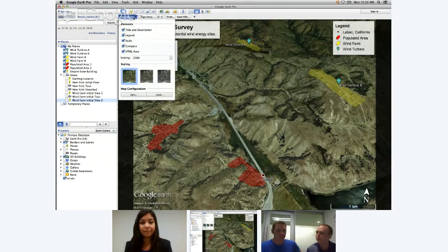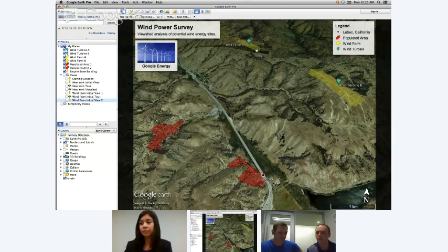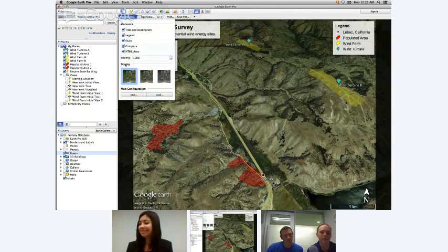There's another really neat feature on the print interface that I'd like to show, which is the color adjustment mode. So you'll notice here I have some yellow KML, some yellow polygons, and some red polygons, and I can even turn on things like roads. So I just turned on roads there. Now, if I print this out directly, in some areas, some colors, it might look a little bit busy, right? So what we've done is we've added these styling options here. Now, there's three options. There's full color, which is what it's set to now. There's semi-desaturated color and grayscale.